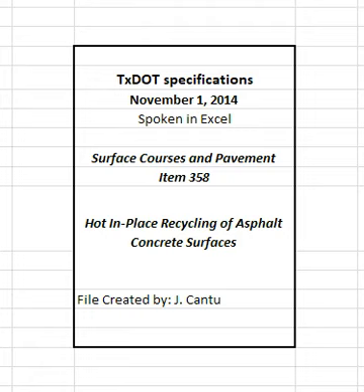Use equipment that is capable of raising and lowering the milling heads to recycle the material around manholes and other obstacles. Equip the milling heads such that they are capable of gathering the heated and loosened asphalt concrete pavement. Operate the milling heads in such a manner to minimize aggregate degradation. Use milling heads that are capable of creating a windrow of the milled material ahead of the mixing chamber or subsequent milling units.